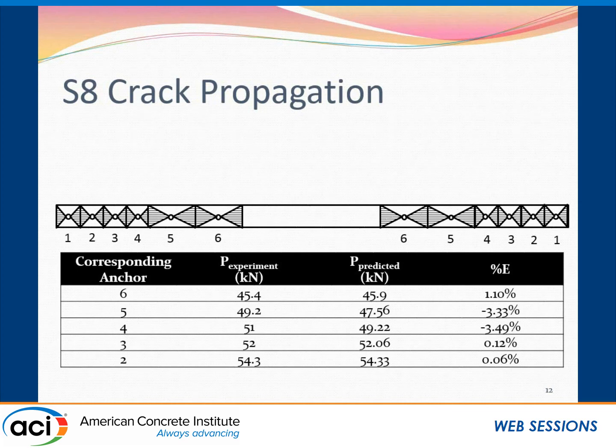I also have a general question. Do you make this FRP fireproof by adding fireproofing to it? As a similar question was asked in the previous presentation, the code takes care of that by utilizing a lower load combination for the beam with FRP. That's how it's accounted for. But there are some fire retardants that can be used, and they are used in the field in order to increase the fire resistance of the FRP.